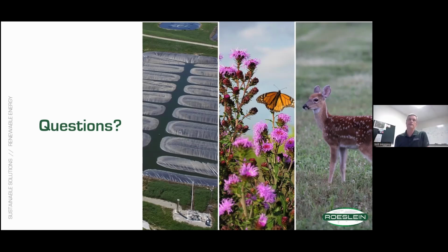And then there are other, I'll say, smaller costs. A lot of our upgrading equipment is not winterized for the severe winters that you probably see in Minnesota. So we might have to upgrade insulation or heat tracing on some of the equipment to make it operable in colder weather.